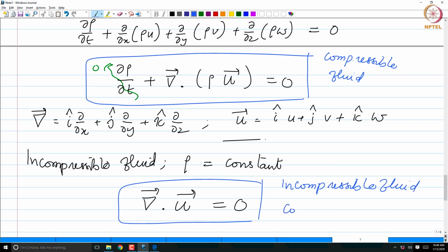That is also known as the continuity equation. Why is it called the continuity equation? Because it defines the continuity of the velocity field. You're taking the divergence of u bar and the continuity is being defined here. It has to be a continuous field such that del dot u bar is equal to 0. That's why it's a continuity equation.